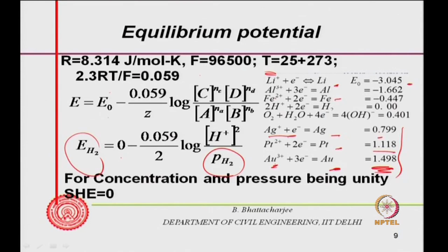So, if you connect Fe with gold, Fe will automatically become anode and gold will be cathode. Similarly, platinum, anyone on this side of hydrogen, if you connect to anyone on the other side, they will tend to be cathode, and the one more negative than hydrogen would tend to be anode. And this is important in sacrificial anode selection and all that. For the typical cathodic reaction in the case of Fe ion corrosion, this is plus 401.